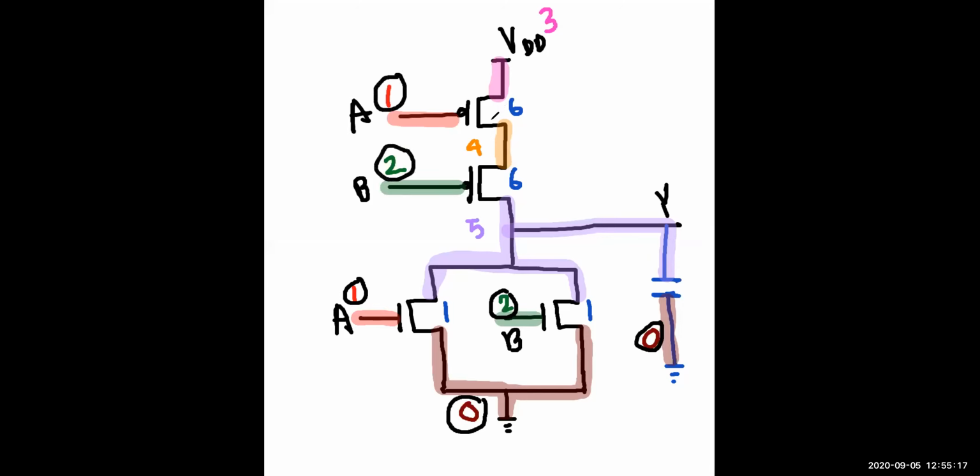This is for the NOR gate actually. So a 2-input NOR gate. So I have given the noding. So this is 1, this is 1, this is 2, this is 2, this is 3. That is the VDD. This part is called 4. This whole part is 5. That is this purple, not the violet color, right? The purple color is 5. Any more? Nothing, right? Yes, sir. Okay.